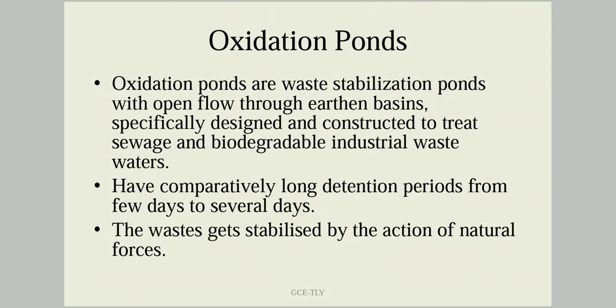Next one is oxidation ponds. Oxidation ponds are also waste stabilization ponds with open flow-through earthen basins. They are specifically designed and constructed to treat sewage and biodegradable industrial wastewater. They have a comparatively long detention period, from a few days to several days.